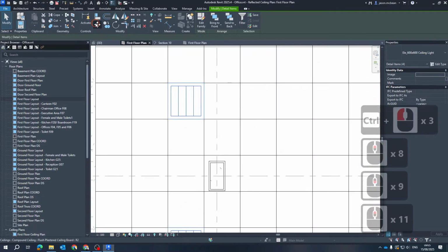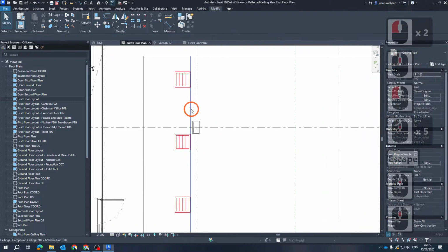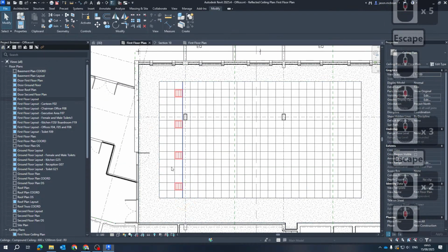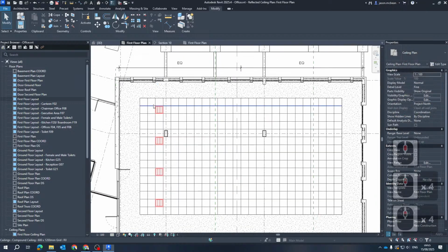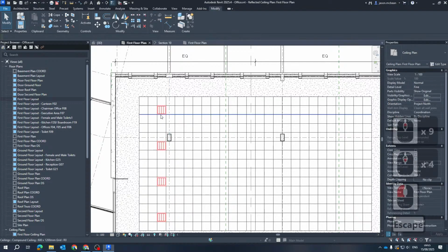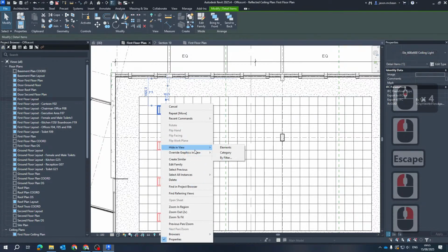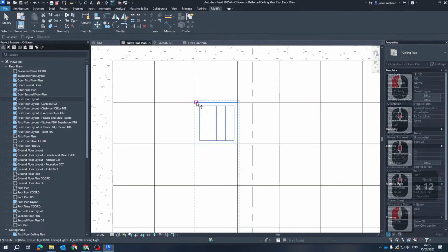What's nice is if I move this now. Doing these ceiling layouts takes a bit of work. If I did this light spacing just like this, I should be comfortable that I'll achieve the required lux level. So I'm just going to grab these again, right click, select all instances in view. I'm going to move them very quickly, so move them back 1.